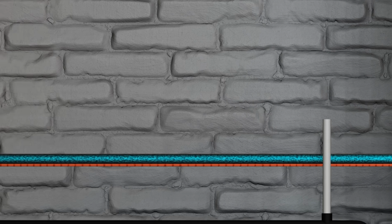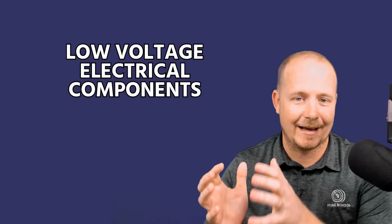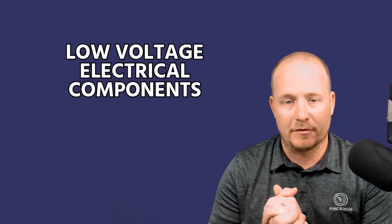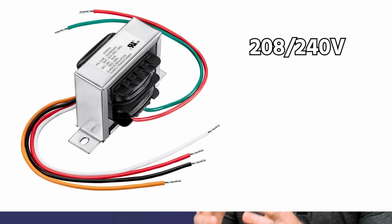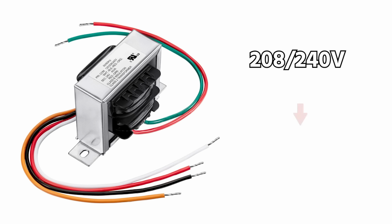All right, now that we're complete with the 3D model, I just want to make sure that we don't miss some of these components on the electrical side. So let's talk about some of our low voltage electrical components that we already covered, but just hit them again real quick. Your transformer's job is to change it from 208 or 240 volts down to a safe 24 volts, which can then be used to control the equipment, your thermostat, your boards, those sorts of things.